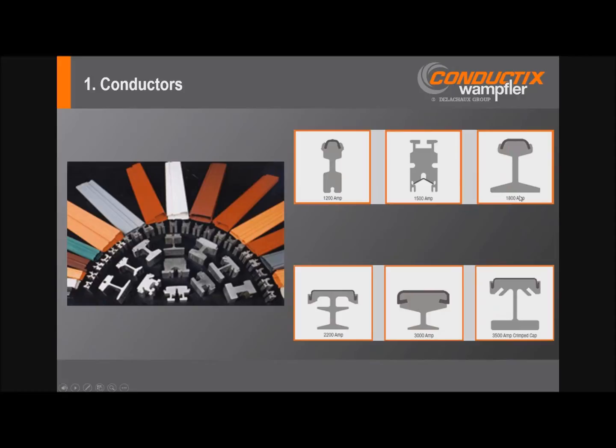Conductors can range in length from 5 to 15 meters, with the length ideally being a multiple of the support spacing, so that the splice joints don't interfere with the hangers. And conductors can be covered or bare depending on the guideway design, environmental considerations, and size of the conductors. The insulating cover materials are typically extruded plastics such as PVC or polycarbonate ABS alloys. And of course, for outdoor use, those need to be UV resistant. And for indoor use, they should be low smoke and toxicity.